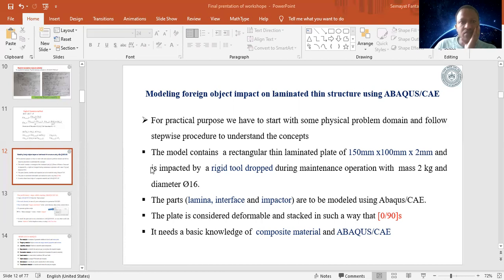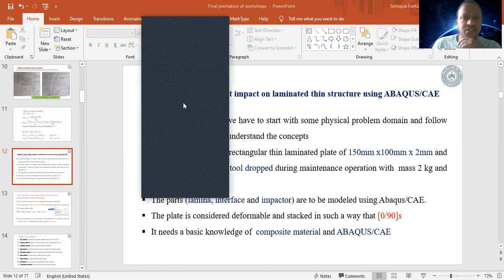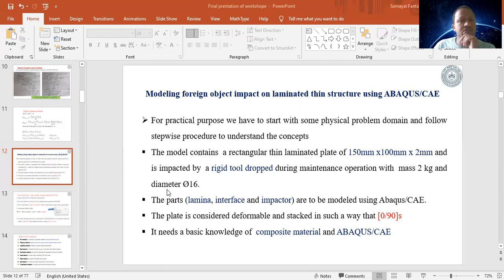So the next is creating the impactor. The impactor is a discrete rigid impactor with shell and revolution. Okay. To create the impactor, I will use a circle entity. Then add dimension to the circle, that is 8 millimeter radius. This is the circle with 8 millimeter.